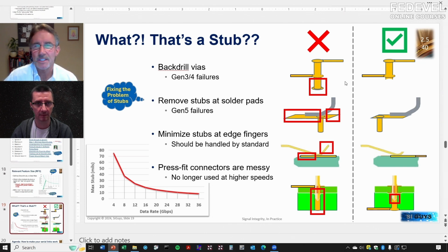You know, I mean, any type of new technology, whether it's equalization or an IBIS model or a back drill, we get the bugs out. We're engineers. That's what we do, right? So here's a picture of a via. I'm really just trying to connect these two traces, right? But I wound up with this stub. Okay, so for very understandable reasons, I get a signal going down here, bouncing off, canceling the signal that's trying to go where it's supposed to go.